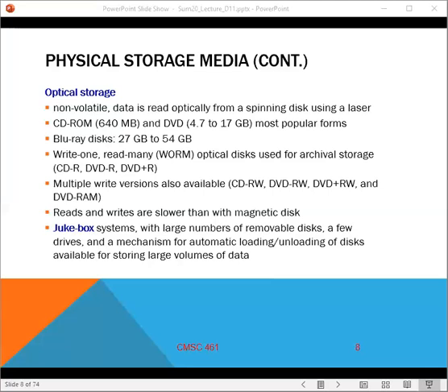Digital information on a CD is imprinted on the surface with pits of varying lengths. The pits are coated with a metallic mirror and a protective layer. And then the region of the surface that is not indented is called a land. Data is read from the disk's surface by illuminating it with a tiny spot of light and then detecting how much light is reflected back from the surface. A change in reflected light intensity occurs every time the laser spot moves from the pit, which has that metallic surface, and the land.